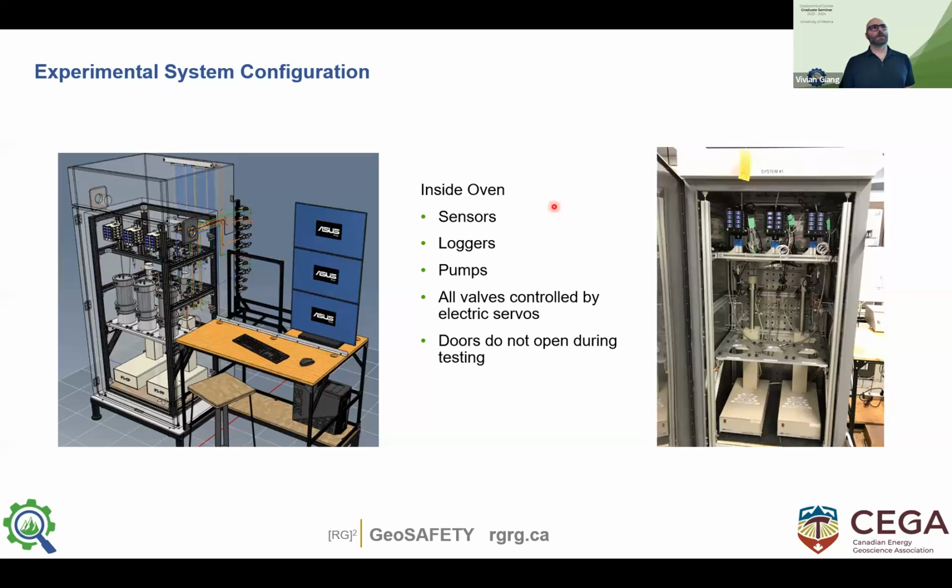The other thing that we noticed, and I'm going to say we because myself, Stephen, Francy, and Hsieh, everybody else in the laboratory noticed that if you have a power supply powering your sensors and you have longer leads going to your sensors, that's a big, long resistor in line. So if the temperature in your laboratory starts fluctuating, the actual power supply to your sensor changes. It's very small. The resistance in your lead changes.